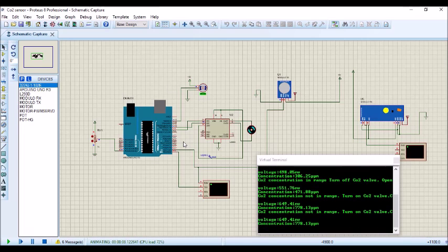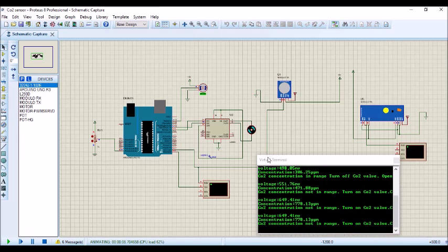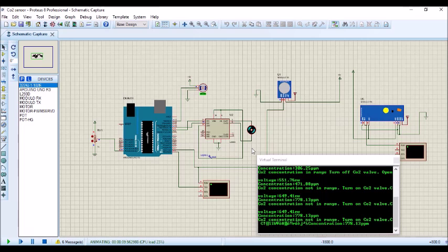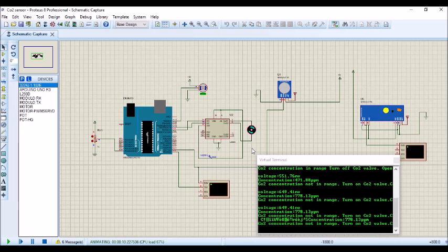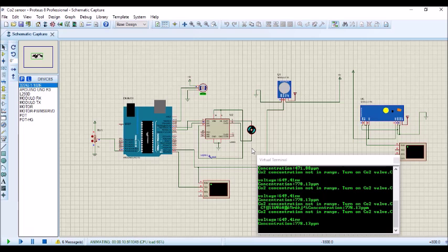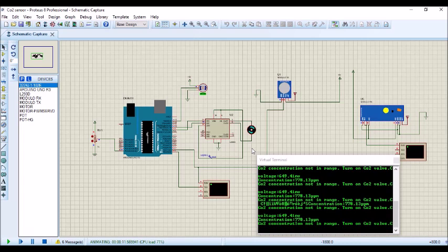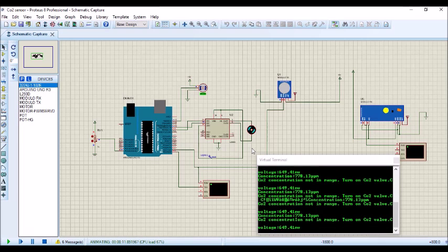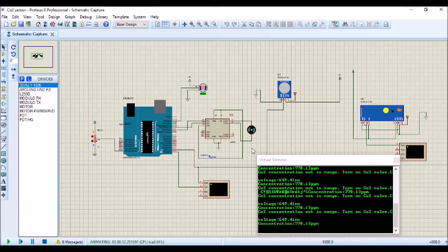Throughout this whole procedure, continuous alert of the live data is sent to the owner or the operator and it contains the data of all parameters. This is done using radio frequency technology where a receiver is used to obtain the data from the carbon dioxide sensor, which is then sent to the transmitter, which is located where the operator is located. The operator will receive the data showcasing status of the level of carbon dioxide in the greenhouse.